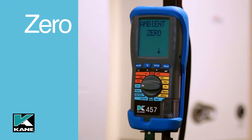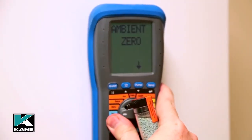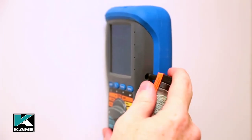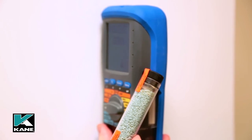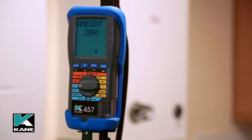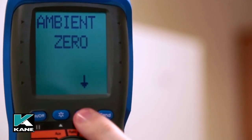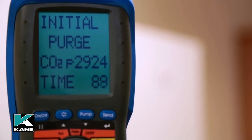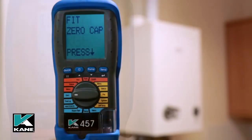The final position in the blue section of the dial is zero. As mentioned earlier, prior to testing and to ensure an accurate ambient measurement of CO2, the KANE457 should always be zeroed using a zero cal capsule. In order to do this, rotate the dial to zero. The display will show Ambient Zero. Press the pump key when in fresh air and the following screen will be displayed: initial, purge, current CO2 reading in ppm, time, countdown for 90 seconds.